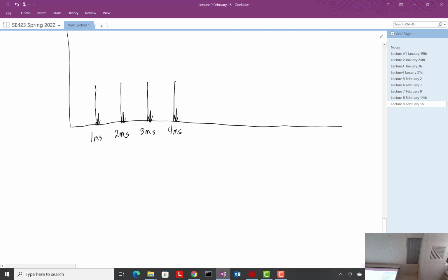Okay? So when we're talking about a millisecond sample rate, doing something every millisecond to control your car and all that kind of stuff, to control the robot, people say, Dan, it takes a while for it to convert. Well, yes, in some sense. But it's just maybe 4 or 5 or 10 microseconds after you told it to convert.